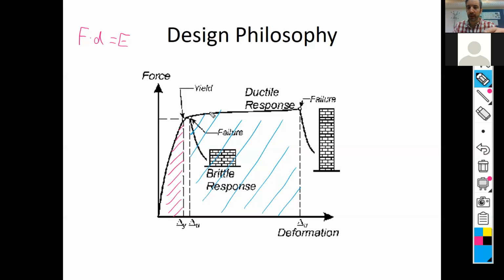So it's just important for you to know that introducing this ductile behavior in a structure, whether it's a bridge or a building, is somehow the physical equivalent of converting the entire structure, or at least parts of that structure, into a damper, okay? A mechanism that is there to dissipate energy, to remove energy from the system, to break down the vibrations, instead of, if the structure is perfectly elastic, the vibrations during an earthquake always increasing.